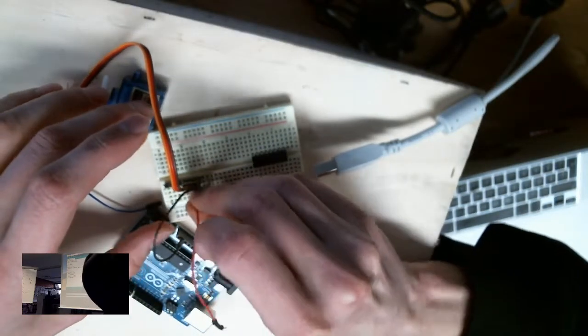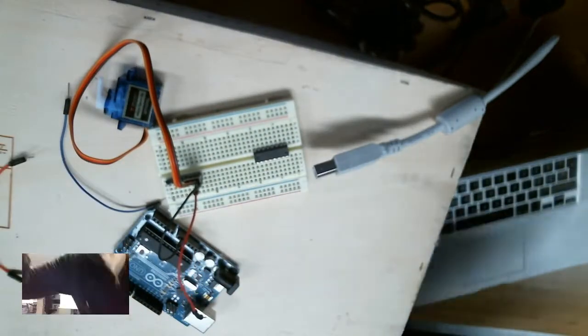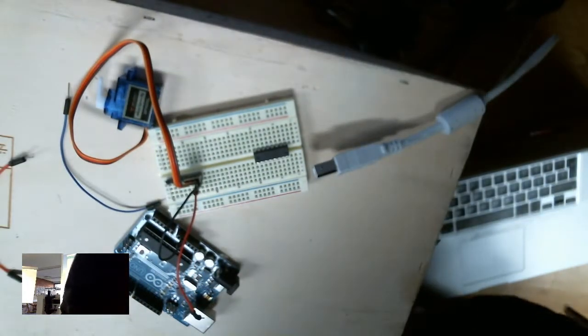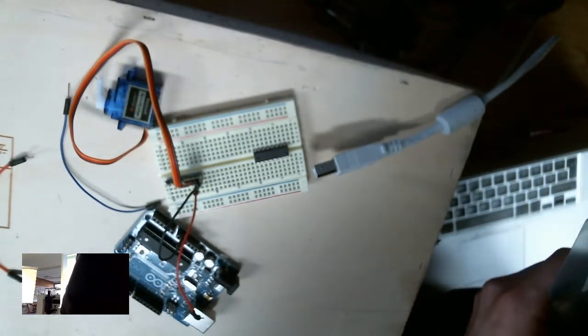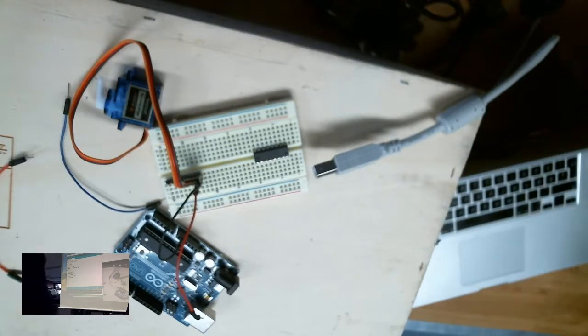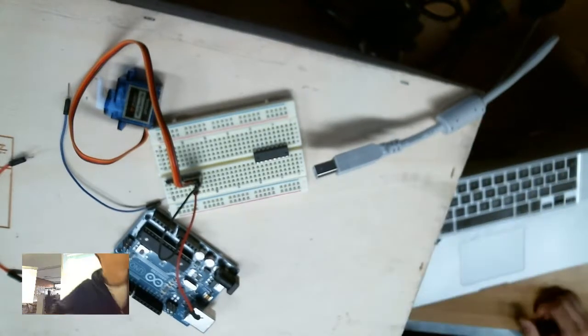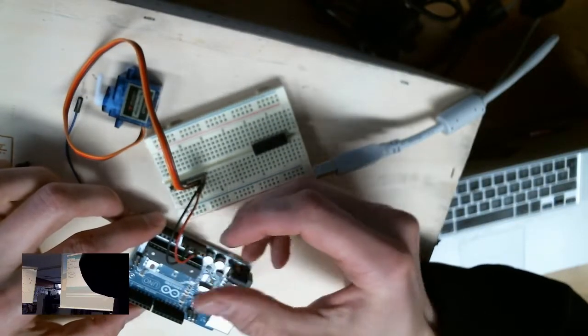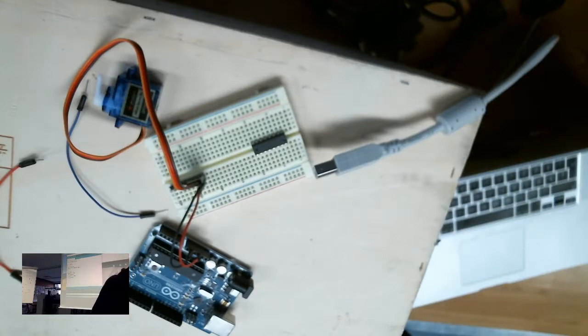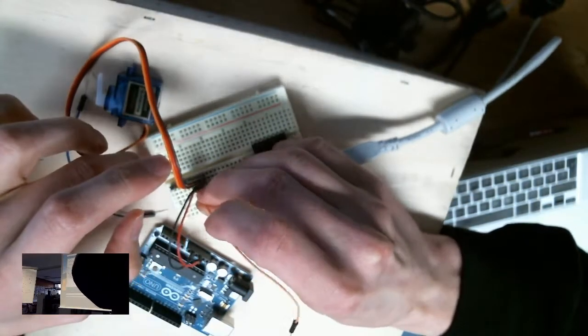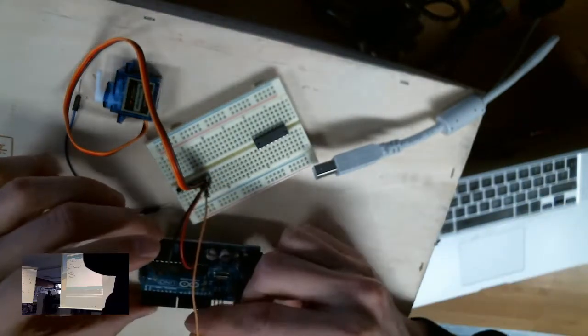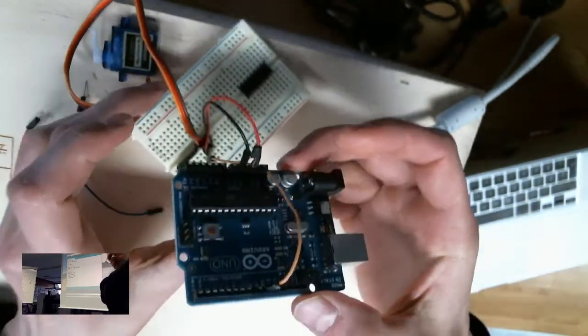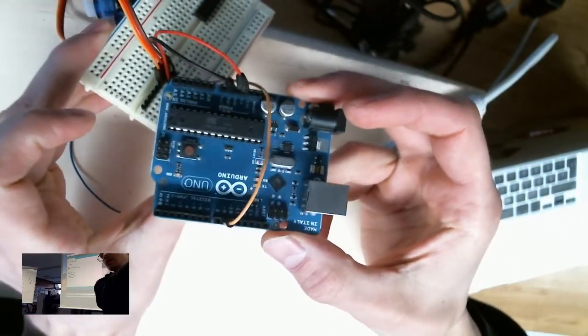Let's do so. Plus 5 volts. By the way, if you're interested, I have these motors, and this time I have a bit more, so you can play around with them. Also plus 5 volts here, and then we need to connect the orange cable. So let's get a decent orange cable, so we can connect it to the actual signal pin, which is pin number 9 as we defined in code. So these are the connections, you can clearly see.